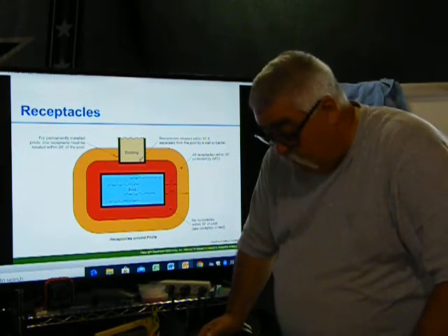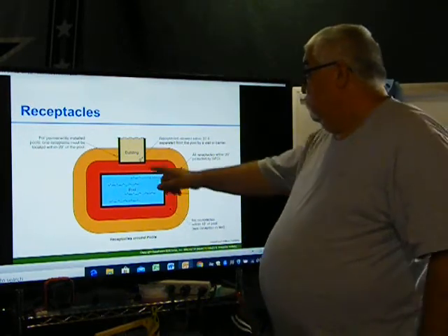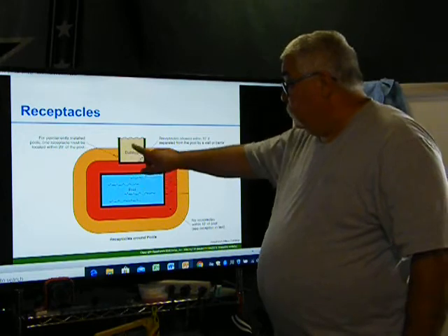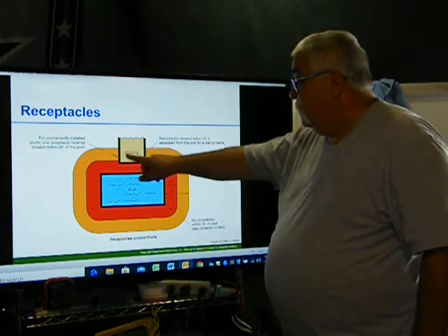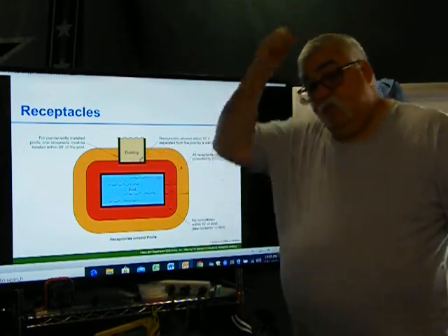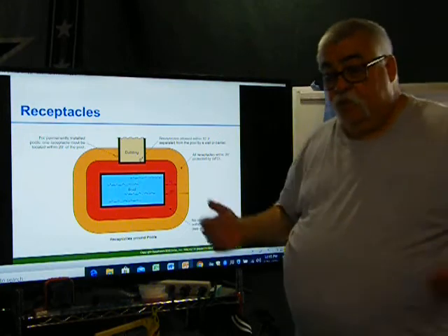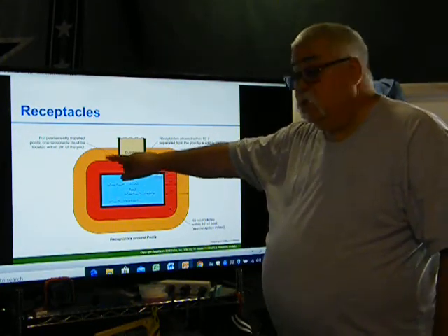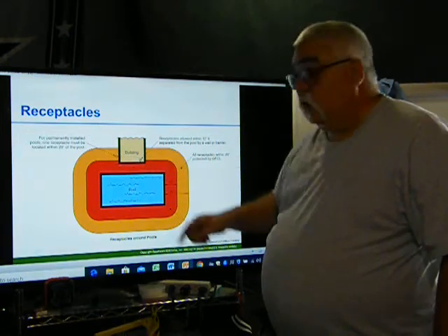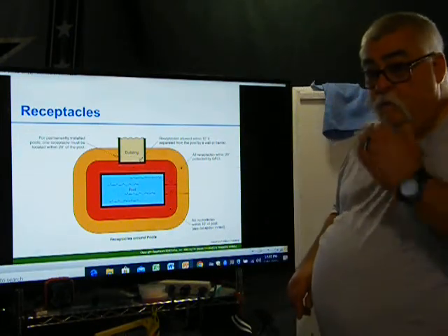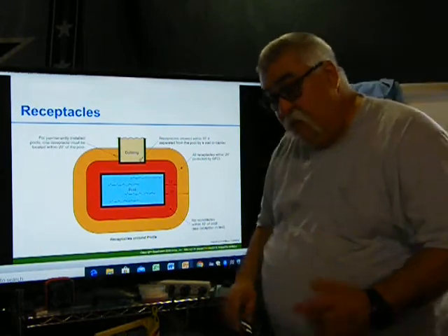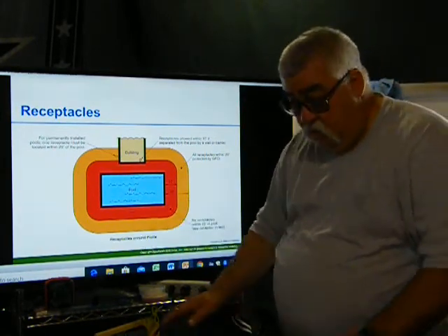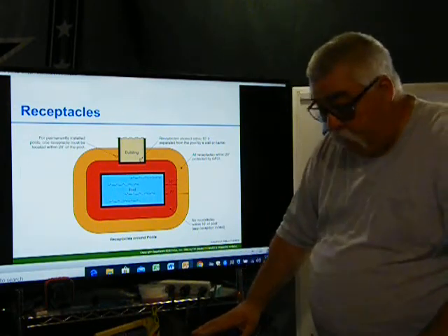And see figure 17. So again, if this wall is closed up, these walls inside the room itself, they're excluded from the code. Not this one. Why? Because this is outside. This one's inside the building. So if there's a wall, then it's excluded. The fence doesn't count because the fence has openings where somebody can reach the electrical, and that could be a problem.